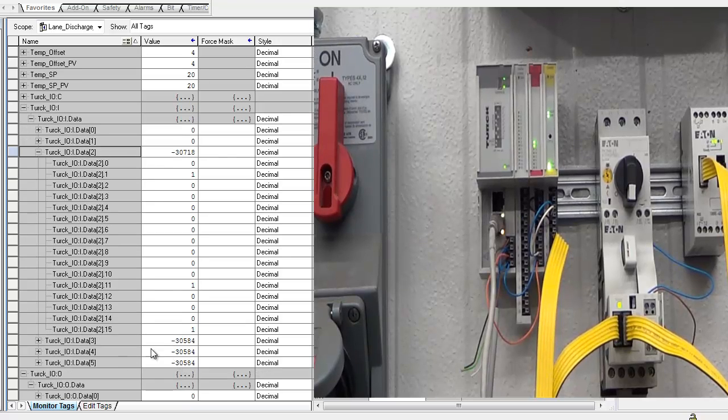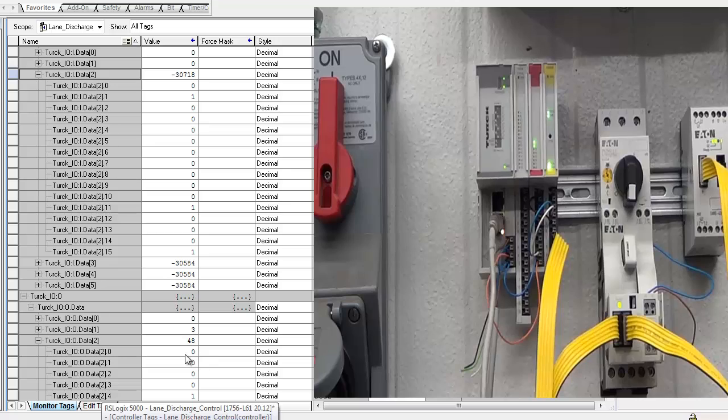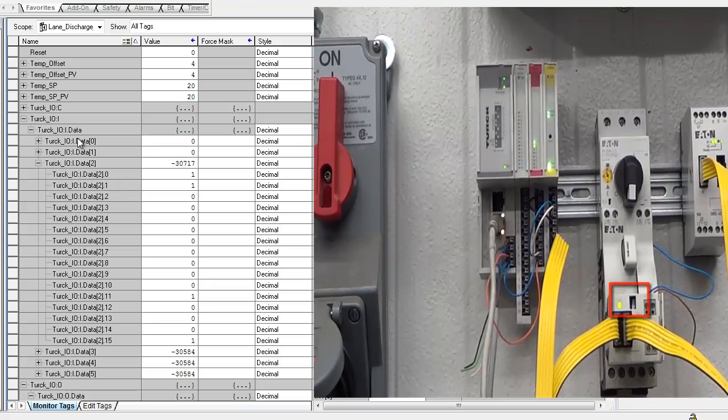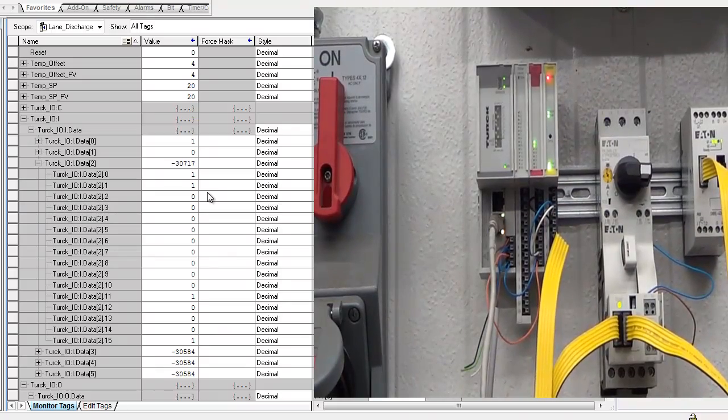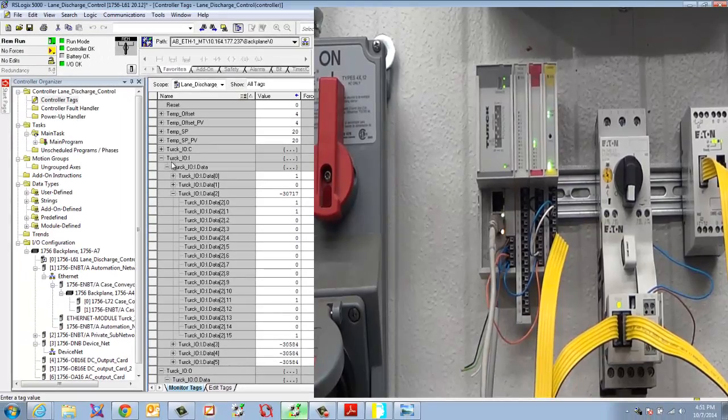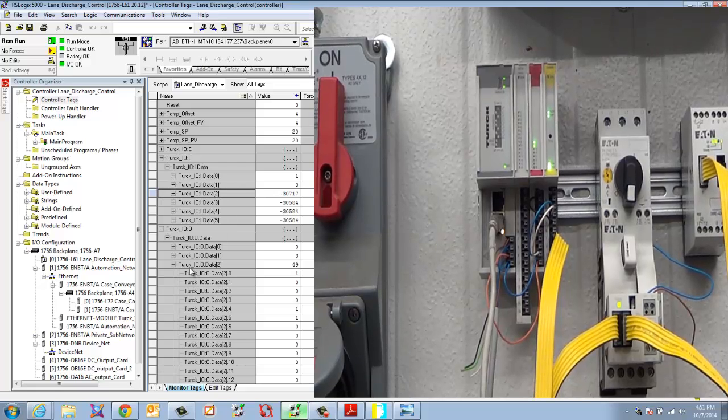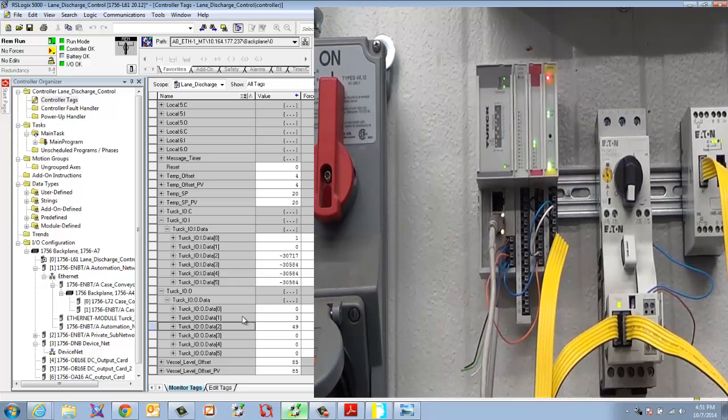Now if I go down to the output, and we'll turn the starter back on, and go up, and you'll see here on the input that there's one there. Now if I turn the contactor off, reach in and trip it itself, you'll see it go out. Turn it back on, reset it, and it comes out. And that's how you can control the modules using this software. Turck's got a pretty good product for setting it all up. And I hope it kind of explains some things for you here. If you have any other questions on how to set the stuff up, let me know.